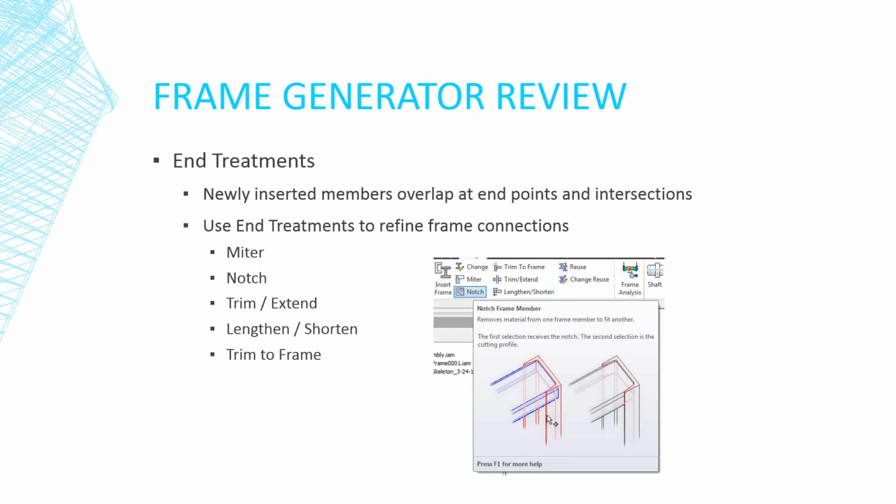I don't know if you use extruded aluminum frames, but my experience has been sometimes we would use the bracket hardware to fasten things, but as often as not, we would counterbore through one member and then tap the center hole of the adjoining member and just screw the frames together, as opposed to using the mounting hardware.